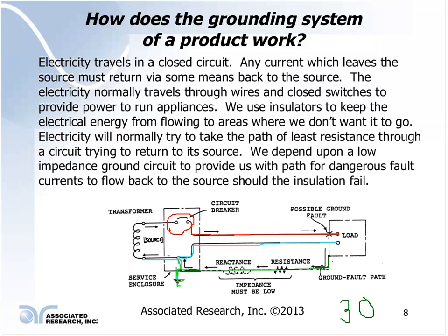If we take that 30 amps and divide it into 120 volts, you'll see that it goes in 4 times. So what does that mean? That means that the resistance of this ground circuit cannot be greater than 4 ohms, otherwise it will never allow enough current to flow to allow my fuse or circuit breaker to open up.